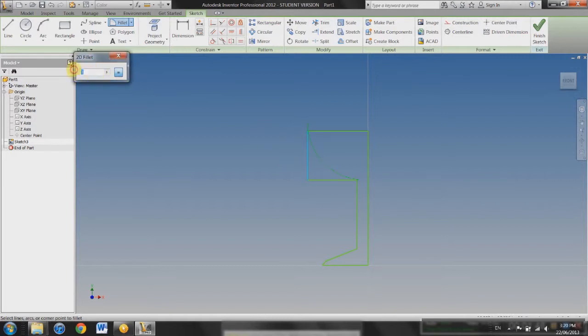If it's too big, go back to 2. There, enter. You actually might have to click on them if you want it to work, so F again. Enter. Okay. Then you can fillet this other edge here, 0.5 should do the trick. There we go. 2 probably works for this one. Yep. Then right in here you might want to go with 1.